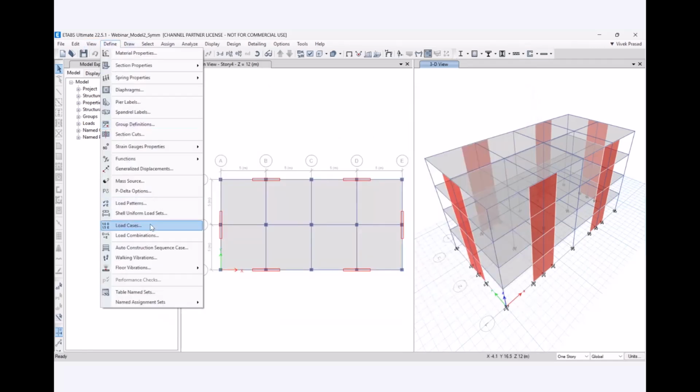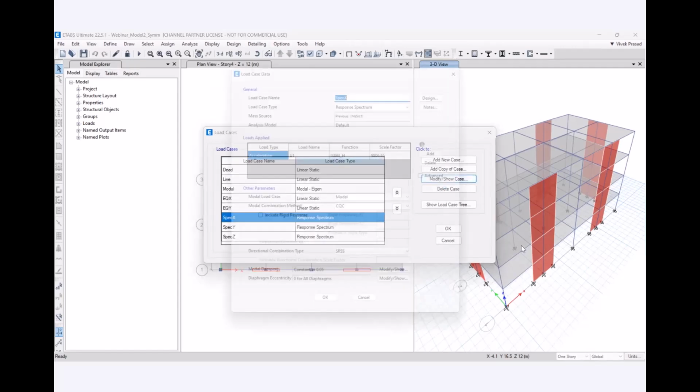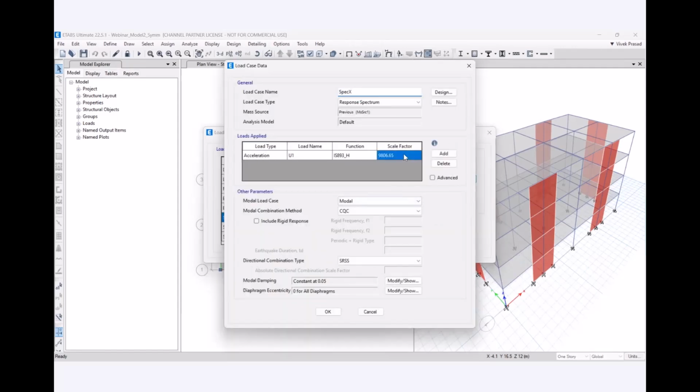Now we'll have to scale the spectrum cases for this. So to this existing, without unlocking the model, you can do this. So analysis results will be lost for these modified cases. That's okay. We are going to rerun the load cases for the updated value. So this one will be multiplied by 1.347.